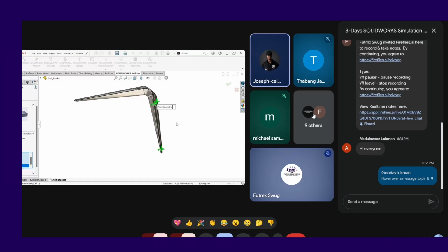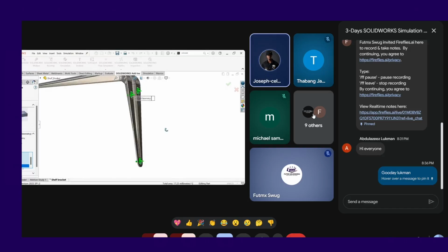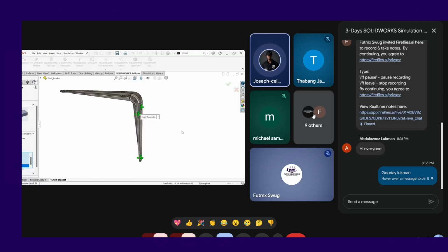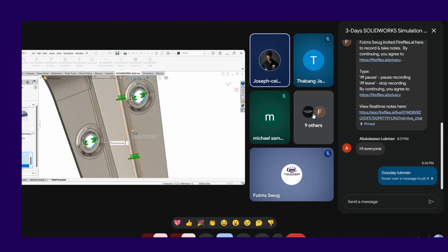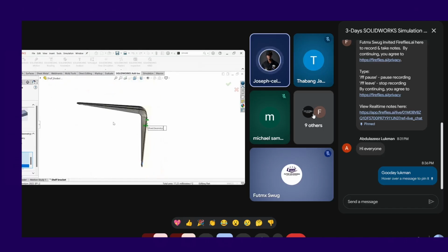Now the question is this: your direction is automatically fixed. Are the fixtures going to be fixed to this side, or to this side? It's basically trying to restrict every single degree of freedom. Ordinarily the part isn't floating in SolidWorks, but it's assuming that it's not fixed.